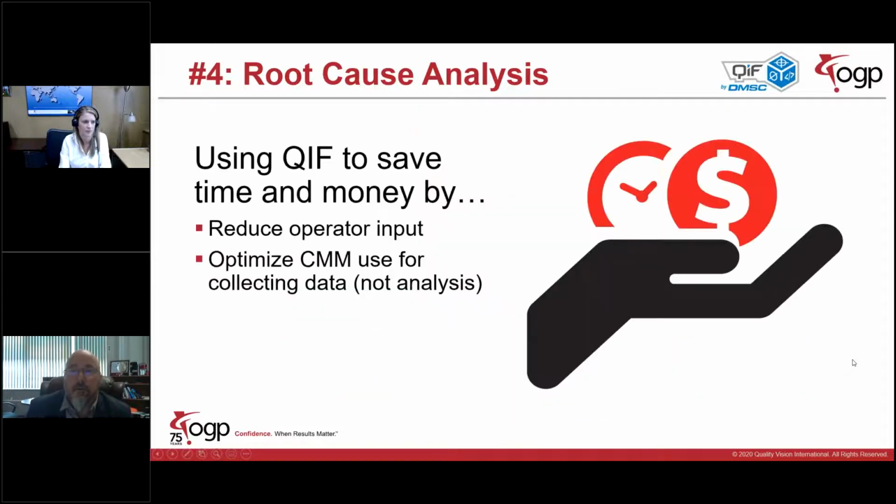So another quick comment, Colby. For those of you that might not have caught it, there's a mapping between the functional datums, which are related to the GD&T callouts that define a good or bad part, and the operational datums that define how to manufacture the part. And that's what's unique about this software: it knows where those are mapped together, so that when I change these manufacturing datums, it is affecting my GD&T results either in a positive or negative way.